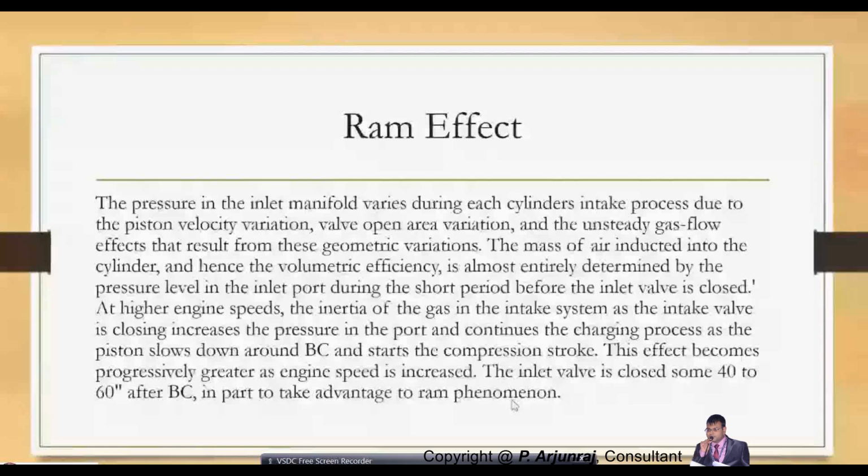The inlet system is basically the intake manifold. How the air is going to flow into the system very smoothly without any restriction, with proper velocity. And you also have the throttle valve, which will open the required quantity of air into the intake system. So you need to ensure that you have proper fine tuning of the RAM effect so that your volumetric efficiency is according to the directions in the specification.